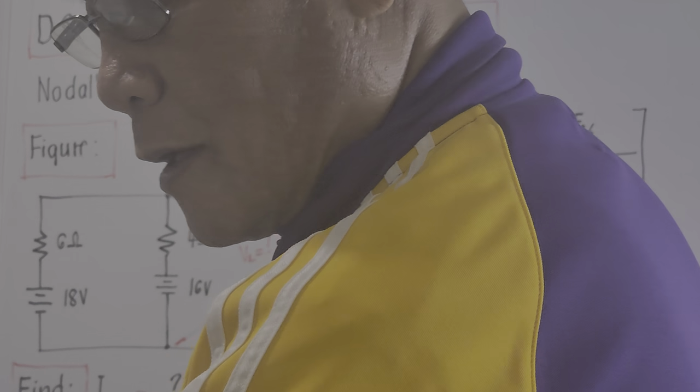To compute the total resistance now, it will be the single equivalent of this one. I am now just verbally explaining the solution, the simplified checking. It will be the single equivalent of this plus 3. That will be the total resistance. So to compute the total current emanating from this 18 volts, it will be 18 divided by 3 plus the single equivalent of this one.